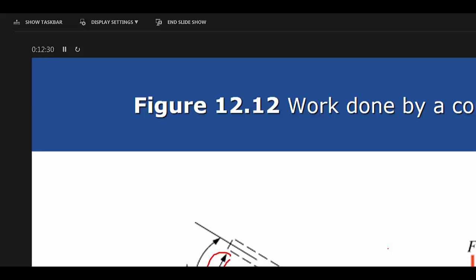Yeah, that's an easy one to manipulate, isn't it? The 63,025 was on the denominator side, so you have to put it on the numerator side. You switch it over, and then the revolutions per minute is in the numerator, so you switch that down to the denominator, and you end up with 19,610